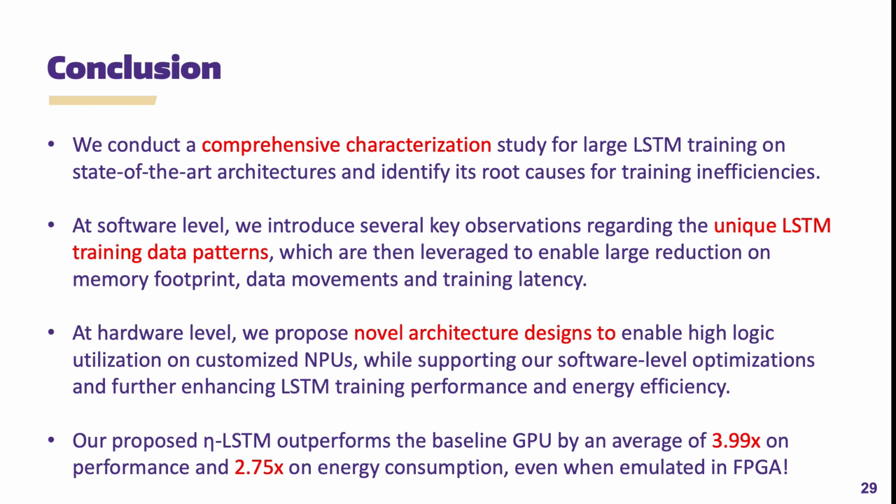At the software level, we introduce several key observations regarding the unique LSTM training data pattern, which are then leveraged to enable large reductions in memory footprint, data movement, and training latency. At the hardware level, we propose a novel architecture design to enable high logic utilization on customized NPUs, while supporting our software-level optimizations and further enhancing LSTM training performance and energy efficiency.